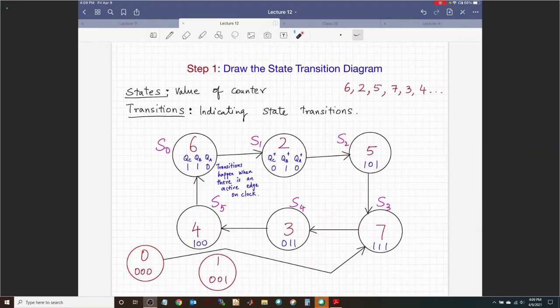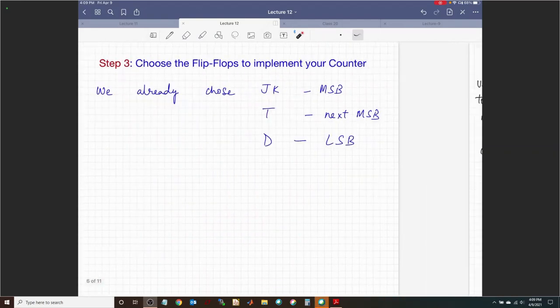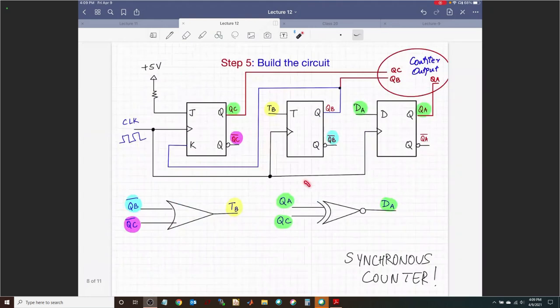So it totally depends on how you have implemented your counter right here, how you have built your counter. So you have got to backtrack it from the K-maps and your circuit that you have built. How do you stop the counter from getting caught in loops that are not intended? You have to force it. Would not happen here, but that is if we toggle 0 and 1.